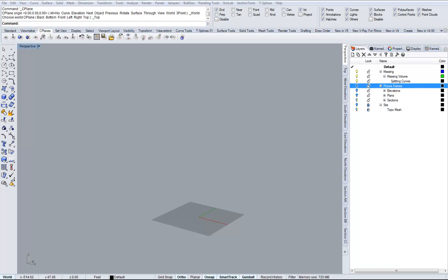Okay, so in this tutorial, I'm going to talk about modeling using a volumetric approach, which, instead of assembling lots of different parts, creates a single volume for the form. What I'm going to try to do is do it without using any kind of transformational commands. We're only going to use the gumball, and the only other commands are probably going to be the split face tool and the merge face tool for the actual faces on the volume.